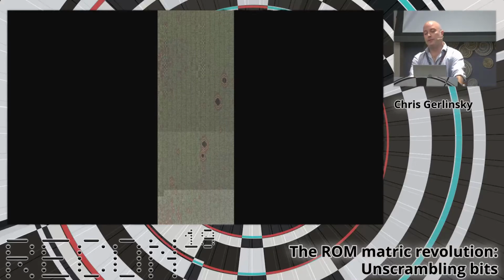That's because this chip I delayered using hydrofluoric acid, and with the wet etching process, you don't end up with a totally planar result. So I have some little holes where the acid etched a bit further. In this case, I don't consider it a really big deal. If I need full ROM extraction, I can repeat it on 2 different chips. Those holes are probably going to end up in different spots. That works quite well. Or another option is to get into polishing a chip instead of using the wet etching.